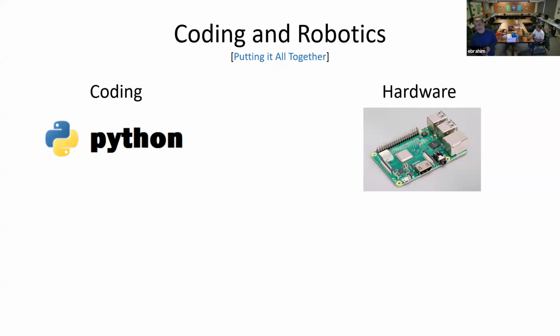Also, what is very powerful about this is that it also has a connector, okay, which is called a GPIO connector, which is a general purpose input-output connector. On that connector, we can connect the actuators, we can connect the sensors on. So what happens here is that on this Raspberry Pi, you can write software that will actually read the sensors, do some intelligence and processing on the sensor data, and then send out information on the GPIO ports to control the actuators to open and close valves and whatever you want to do. In our case, we're going to control servo motors. Okay, so that's basically how powerful this is.